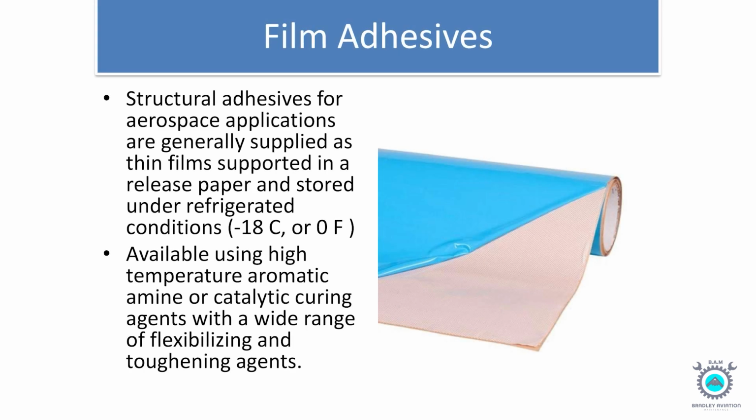Film adhesives. Structural adhesives for aerospace applications are generally supplied as thin films supported on a release paper and stored under refrigerated conditions, minus 18C or 0F, available using high-temperature aromatic amine or catalytic curing agents.